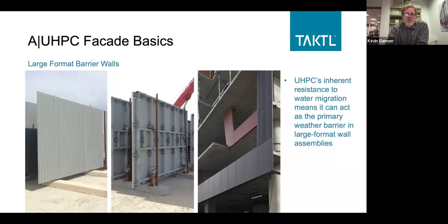This is welded tube steel frames that, if it was spray-in GFRC, those frames would be lowered and registered to a mold, and then they would have little steel hooks welded off of those steel tubes, and then they would just spray in, and the sprayed GFRC would be basically bonded to its frame.